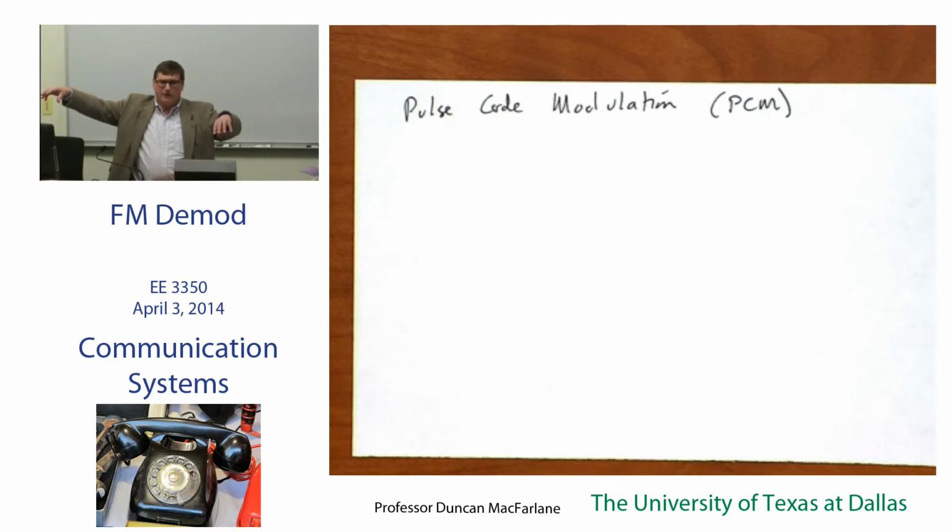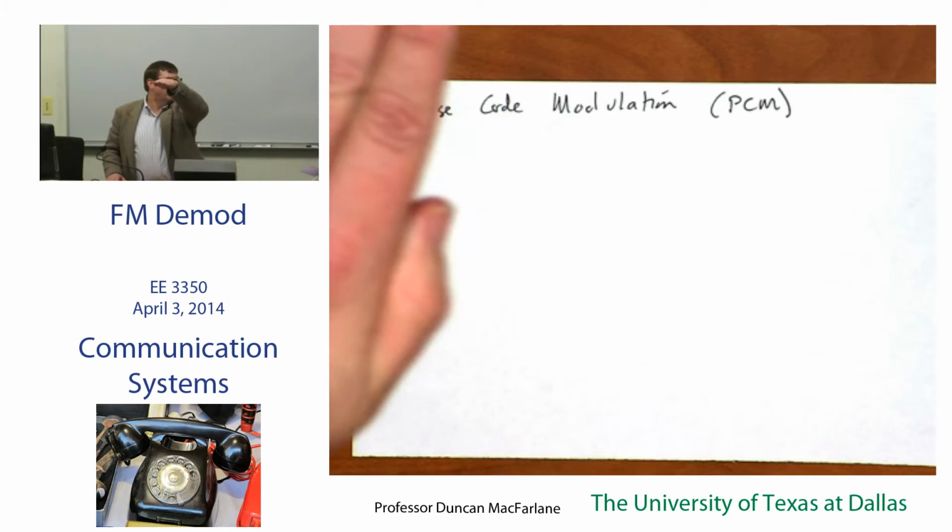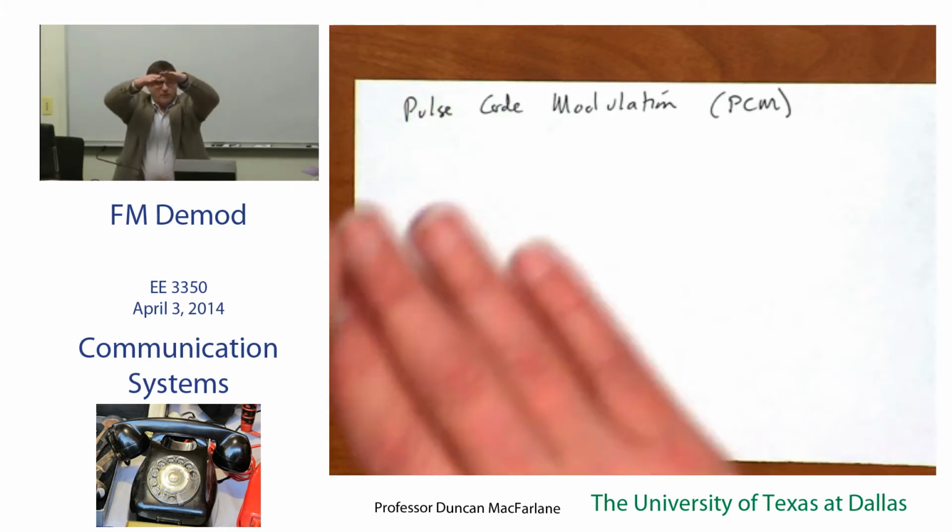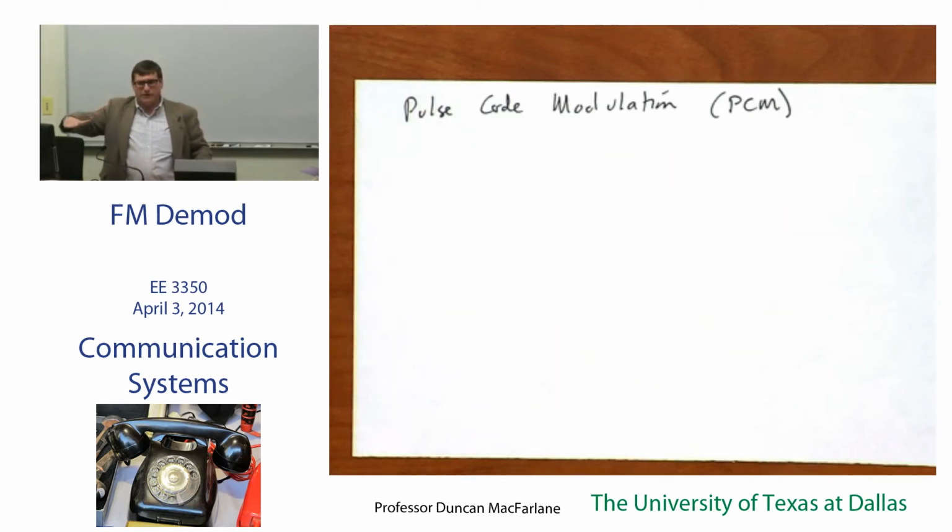Every 100 kilometers along the way, my signal would drop 2 orders of magnitude, but then I would see an amplifier and it would raise up 2 orders of magnitude. It would propagate another 100 kilometers, degrade 2 orders of magnitude, and then bounce up again. It'll make it to Chicago fine after 16 of those. Attenuation, amplification.